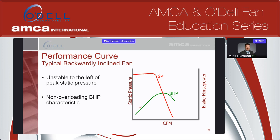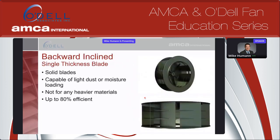And then you'll see here a key characteristic is the brake horsepower curve. If you select a motor over this brake horsepower, at this specific speed, you can't ever exceed, no matter where you're at on the fan curve, you can't exceed that brake horsepower. So it's a nice feature versus the radial fan where it's linearly increasing, and it just kind of goes up with flow. So this has a cap on it at a specific speed.